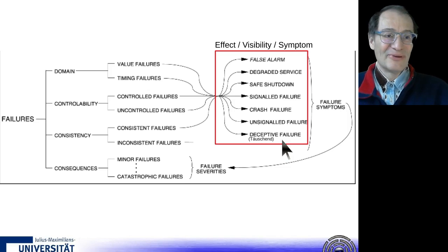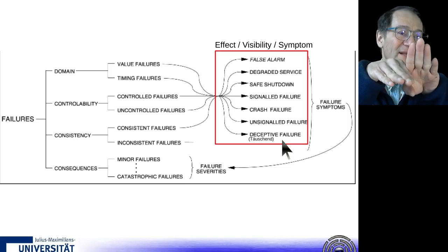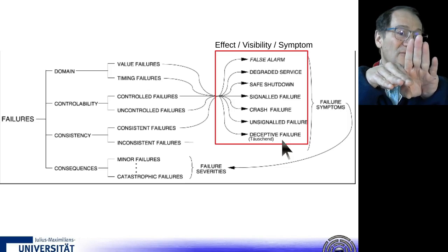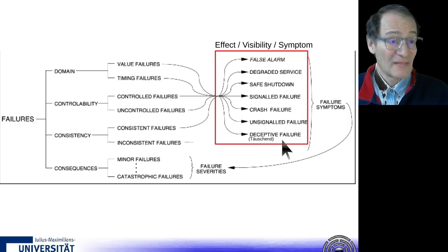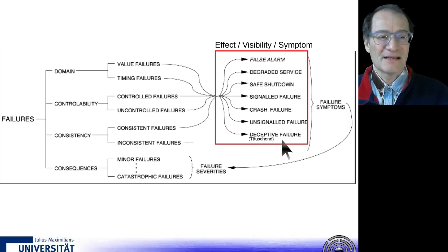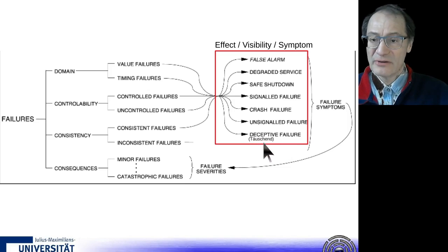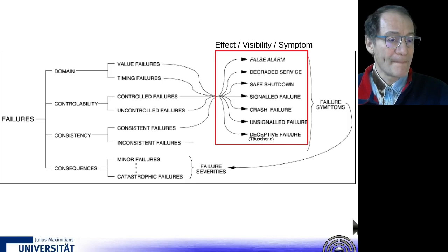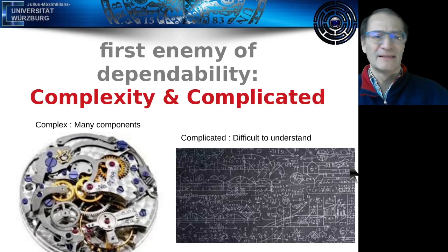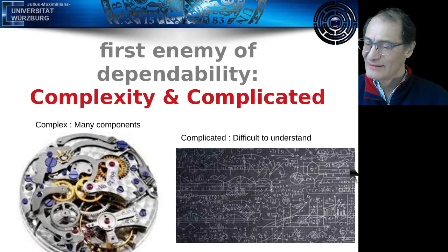And then you think, okay, everything okay, but if you are increasing the angle of attack too much, then you can have a stall, and then the aeroplane will fall down, and you have an accident. So this is the reason of, I know at least two or three such cases where the angle of attack sensor froze. It was reporting data and saying everything is normal, but this data was wrong. So deceptive failure.